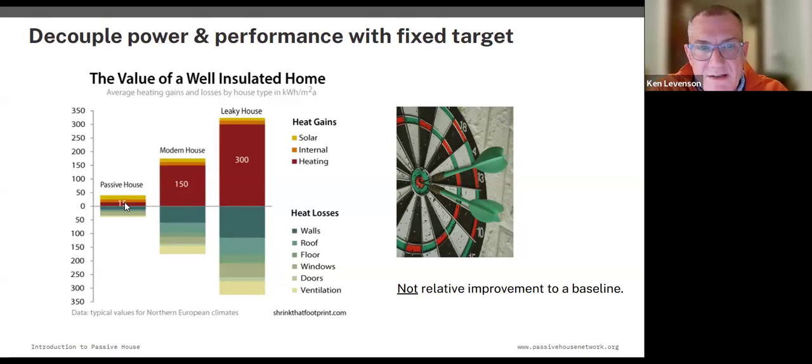It's important to show that there may be a little bit more solar gains here, but these are not completely solar dominated, and we're not trying to make a passive solar house in the classic sense of looking back at the 1970s. Great buildings, a lot of neat stuff going on, but we're really trying to control those solar heat gains and prevent unnecessary overheating, calculate that, and really squash the actual heating that we need to do.